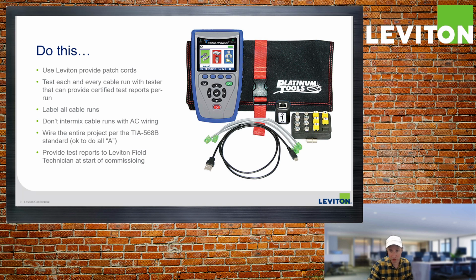Other things you should do: test each and every cable run with a cable tester that can provide certified test reports per run, and label all the cable runs. Those two things go hand in hand. When you do that testing, provide that test report to the Leviton field tech when you get there. You will get a pass-fail on every wire. Anything that fails, fix it before we get there. Most testers will also give you a run length, so you can get a nice report of every run and how long it is. So it gives you a quick way to validate that you haven't gone beyond your allowed maximum run length. Okay, helps us a lot.